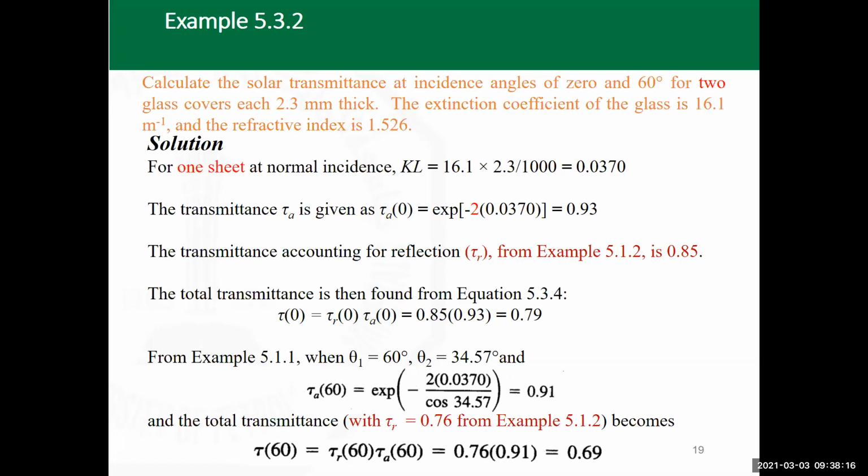If a normal flat plate collector can be used for heating water to 70 or 75 degrees centigrade, an evacuated tube collector can increase the temperature to something in the order of 130, 150. A flat plate evacuated tube collector can even bring it to 180 or 200 degrees centigrade. I'm talking about this kind of collectors that are commercially available, without going to the concentration of the collectors. I'm not talking about concentrated type collectors that can bring the temperatures to values that are much higher than that.